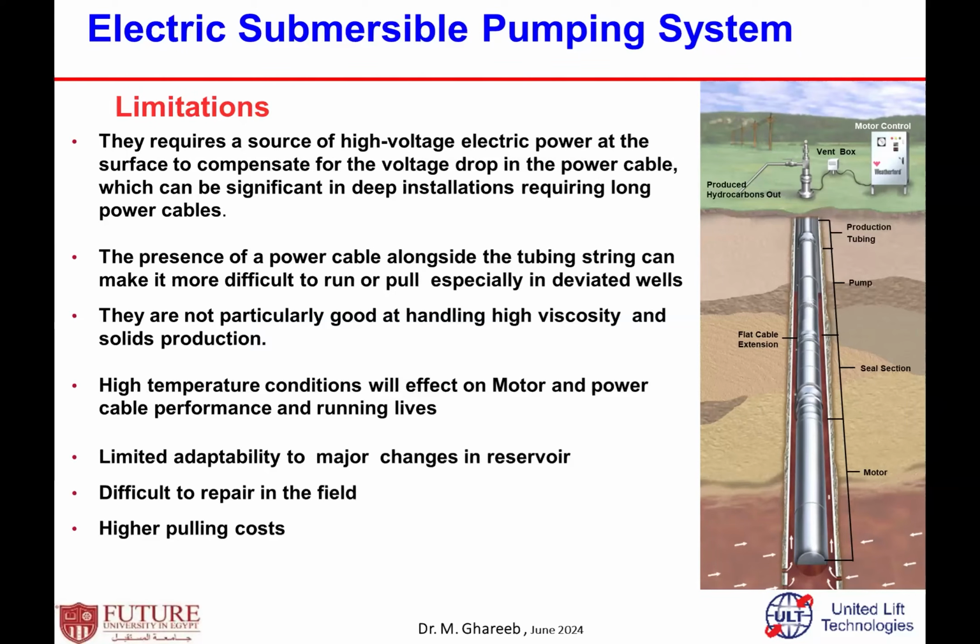If you run with a 1-inch cable, then the total size of the cable plus the coupling will be around 5.5 inches. With the casing at 6.25, that leaves around 1 to 1.5 inches between casing and cable, and if you divide that on all sides, it's a very small area.